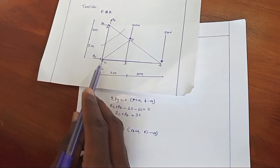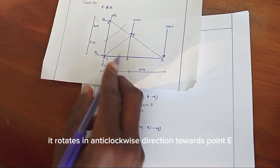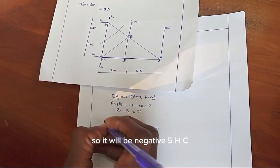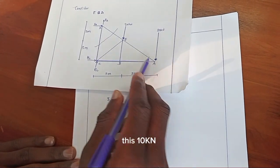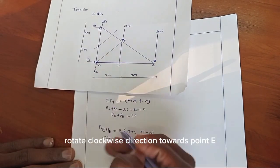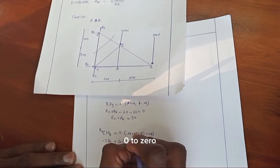Now HC rotates in anti-clockwise direction towards point E, its perpendicular distance is 5, so it will be negative 5 HC. This 10 kilonewton rotates clockwise direction towards point E, so it will be plus 10 times 5, perpendicular distance 5, is equal to 0.